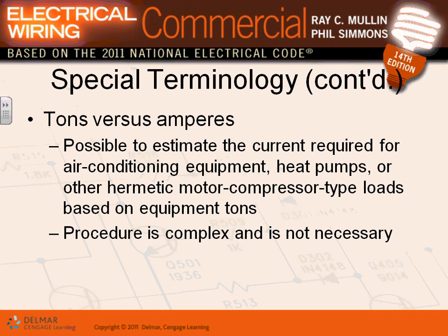When we deal with tons versus kW, usually we deal with the mechanical engineers who tell you this is a 500-ton chiller, how am I going to convert it into kW? Every manufacturer has a little factor that converts it directly into kW. If I have kW, I can assume, say, an 85 power factor and size it from there.